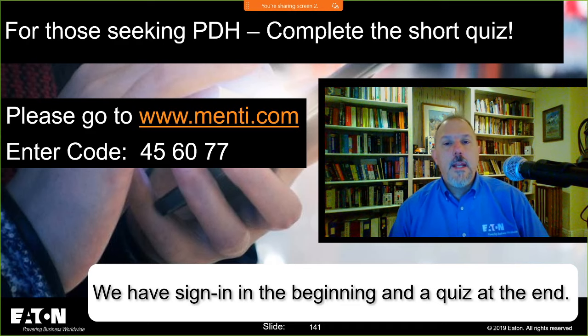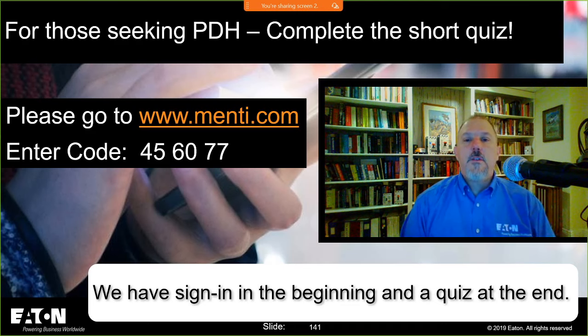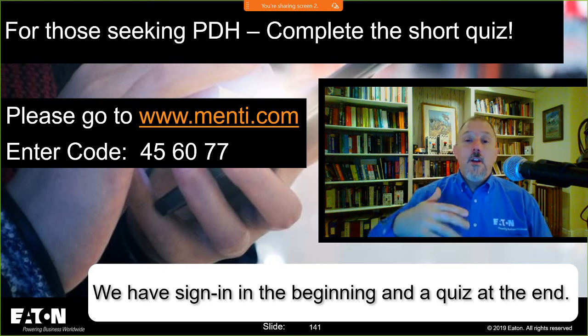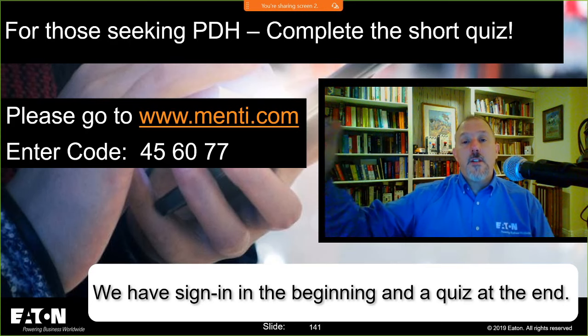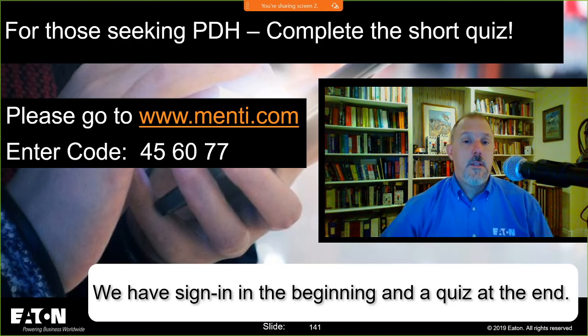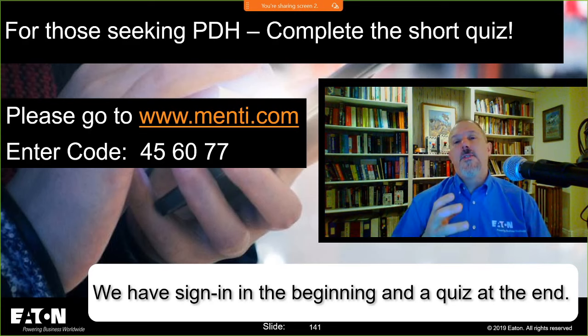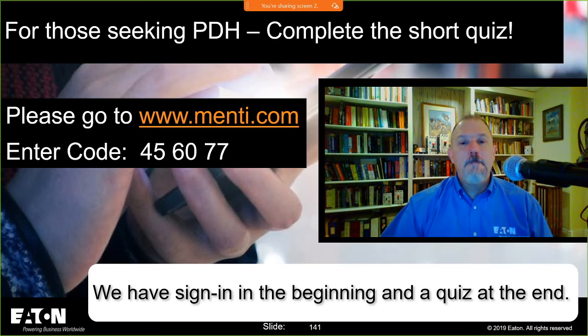X/R rating 6.6 for testing breakers may be different than the power system X/R ratio. That is correct, and it'll be different. You just don't want to have an X/R ratio greater than 6.6, which is really hard. Really hard. I say that because it happened to me once. And I was doing a system, I missed it, but that's okay.